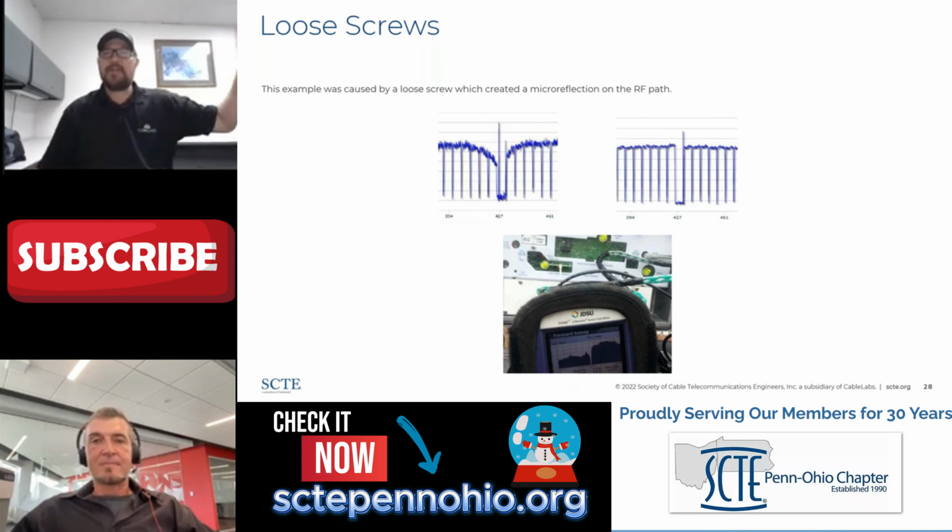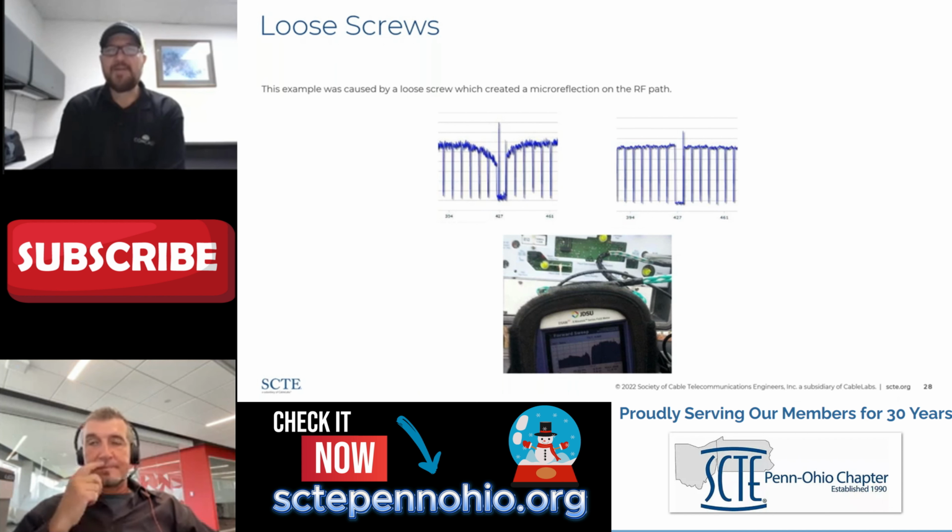So it'll increase the output power of the channels that are not affected, which then increases the input to the next amplifier and can cause that amplifier to go into compression or distortions, which would affect every channel in the lineup, regardless of whether it's part of the suckout or not. So suckouts are important in and of themselves, but if they influence the ALC pilot, they become exponentially more important.